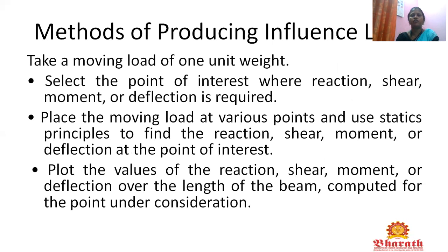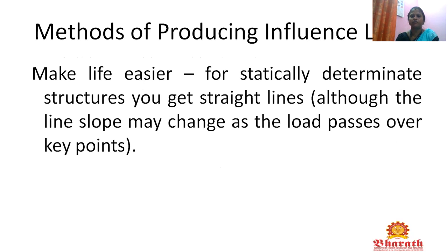Next is the method we are going to see for the influence line diagram. First is taking a moving load of unit weight. Next, select a point of interest where reaction, shear, moment or deflection is required. Next, place the moving load at various points and use statics principles to find the reaction, shear, moment and deflection at the point of interest. Next, we plot the values of reaction, shear force and deflection over the length of the beam and compute the point under consideration.